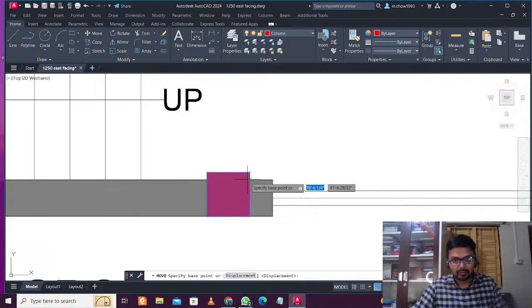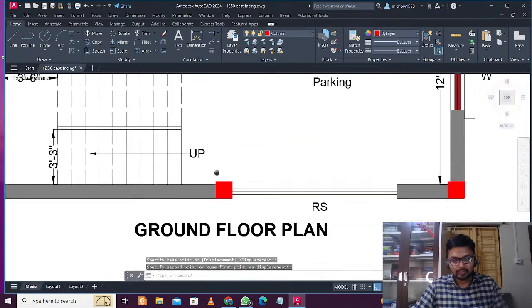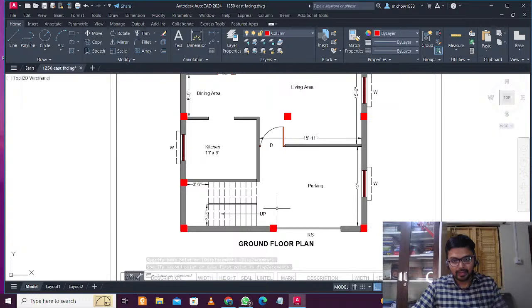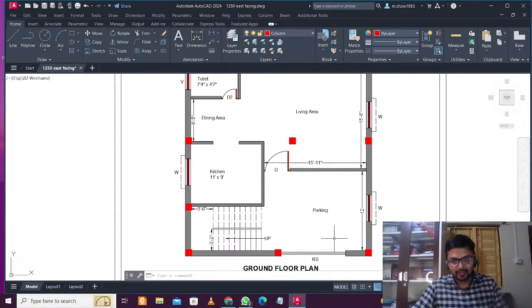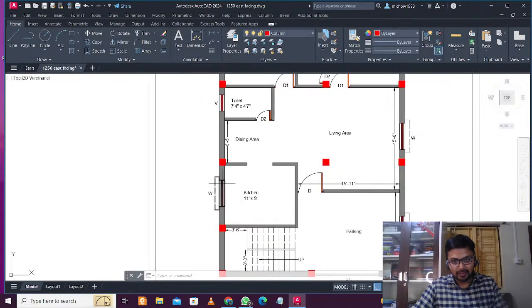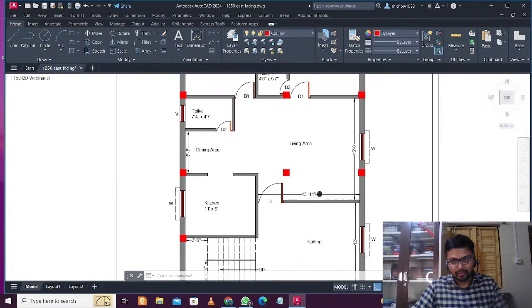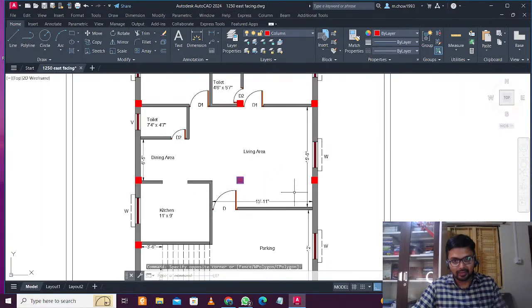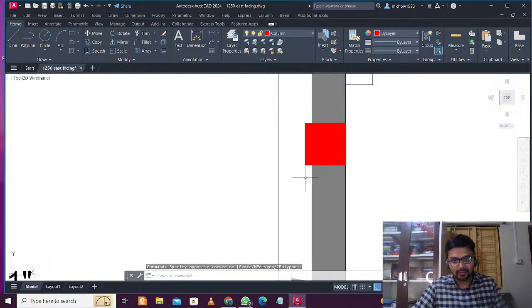Let's select this point. Okay, fine. Don't want any column in this point. 3 columns is okay for the staircase portion. So in this portion we can have a support here, landing beam here, and second cantilever we can have that, no problem in that. Okay, so in this portion we have to decide where we want to go. So let's go in the third layer, and let's keep this.